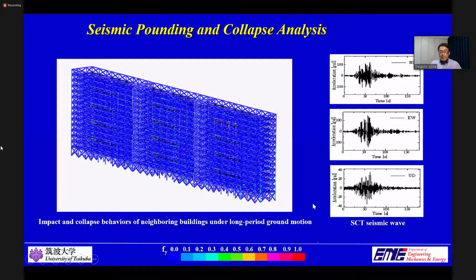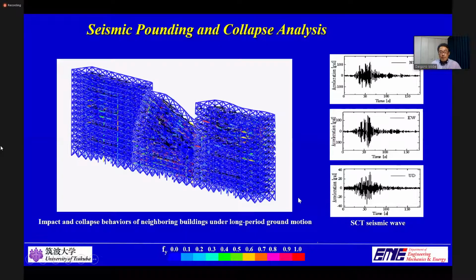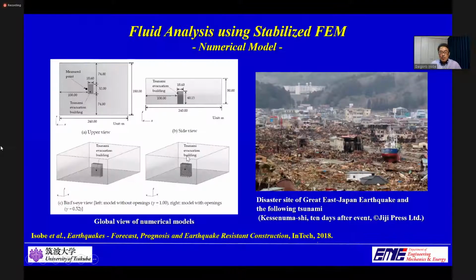We also performed a continuous analysis of a steel frame building subjected to seismic excitation, followed by an input of tsunami wave and collision with debris. A numerical code using the stabilized FEM based upon the volume of fluid method, which indirectly expresses a free surface shape by function values, was adopted for the fluid analysis.